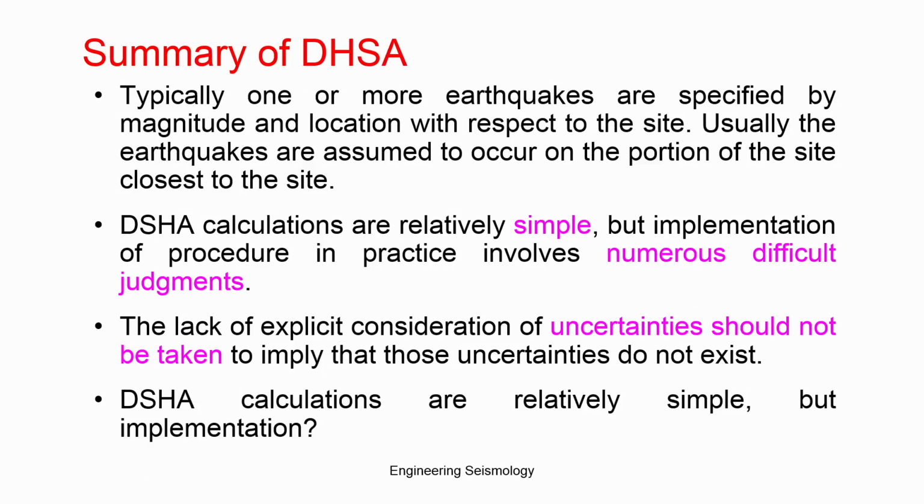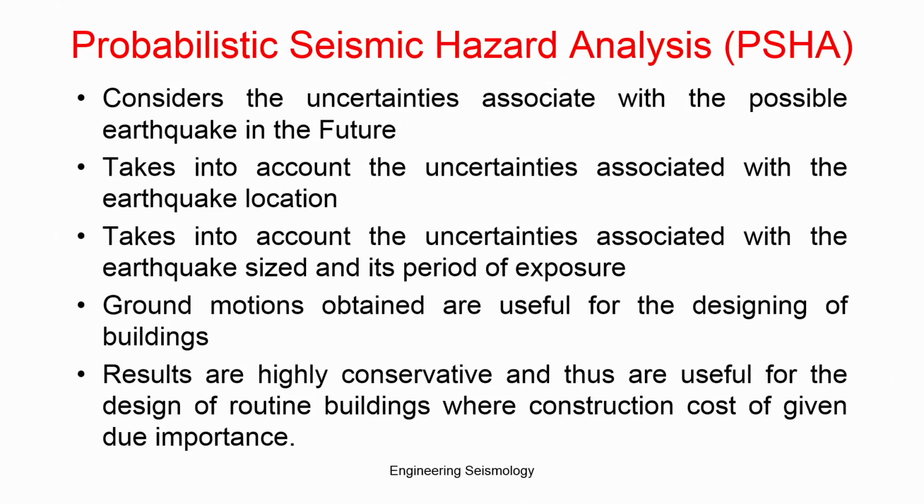DSHA calculations are relatively simple, but implementation of the procedure in practice involves a number of difficult judgments. The lack of explicit consideration of uncertainty should not be taken to imply that those uncertainties do not exist. DSHA calculations are relatively simple, but implementation wise it is very expensive. So, in order to overcome that, probabilistic seismic hazard analysis has been developed, where they try to consider the uncertainty associated with the different parameters or components of the hazard analysis and try to quantify that uncertainty mathematically.